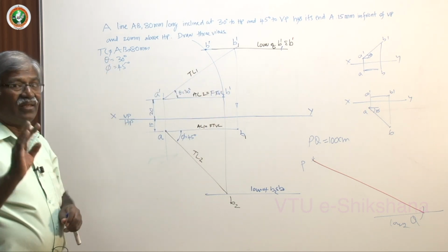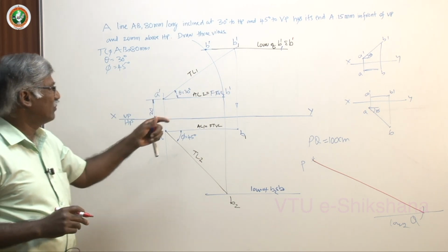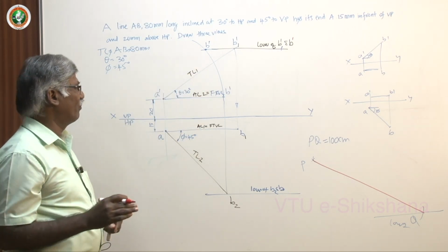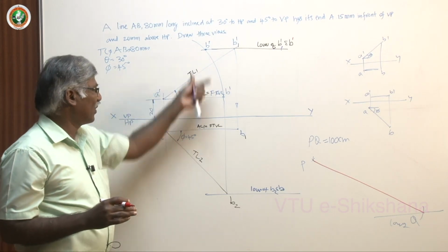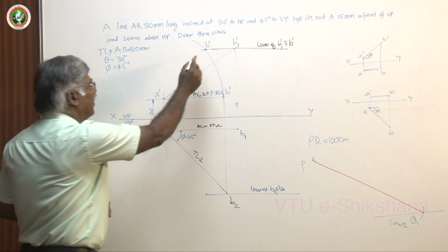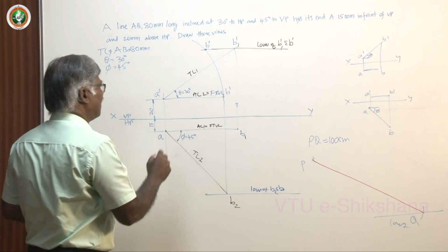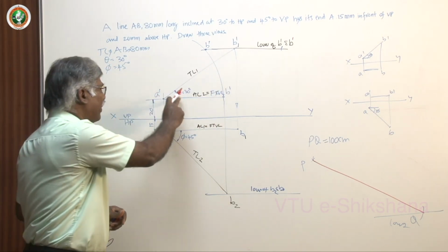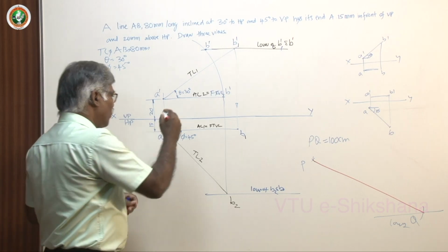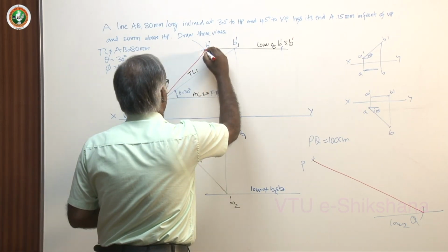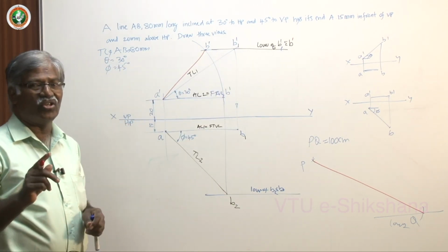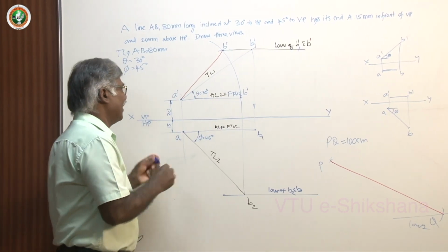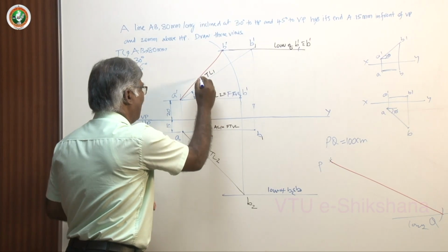There are three paths that are important here to understand the concept of straight line. You can work any problem on straight line. I will tell you after completing this. A dash B1 dash is the initial position and true length at true inclination. If you join this, you will get the final front view position and the angle. This is called the apparent angle. Actually, this is not the actual angle, it is the apparent angle.